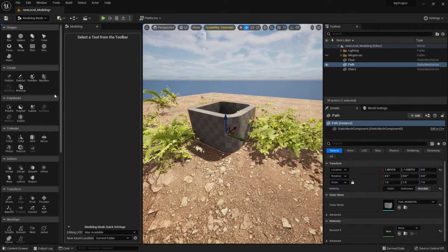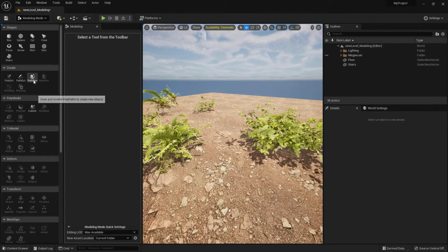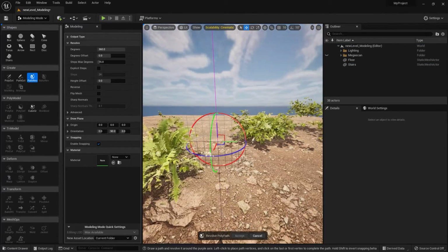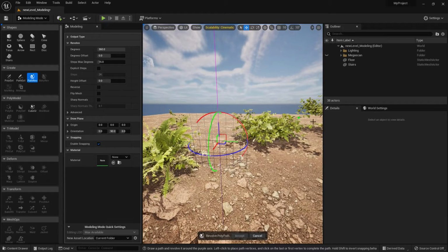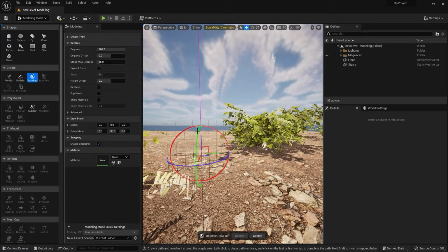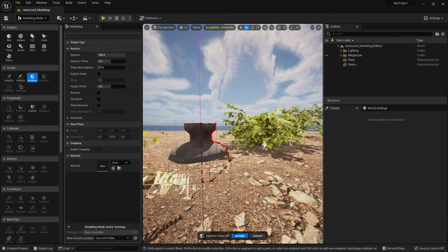It just makes sense. Another one is path revolve, which allows you to create a profile. Let's say I want to put a jar right next to my staircase. All I need to do is to go in here and try to think about, all right, how will I be able to create a profile for that jar? So I'm just going to create one like so, and I end it somehow in the middle of the axis. Go and close that, and voila, I get to have that jar created in no time.